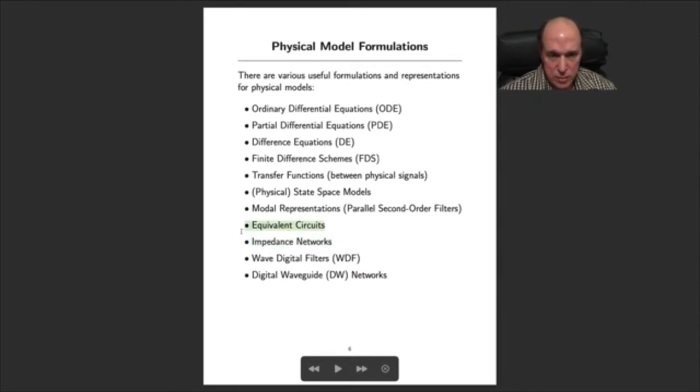Once you have your equivalent circuit, you can replace every element in the circuit by its impedance. And if it's a linear time invariant circuit, you can do very elementary resistor analysis of the network, because you can manipulate the complex impedances of things like inductors and capacitors as if they were resistors when you're in this impedance space.